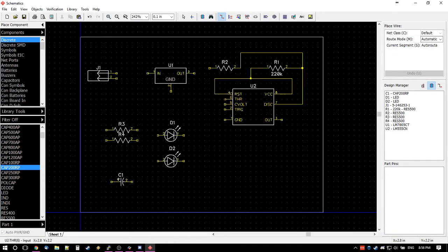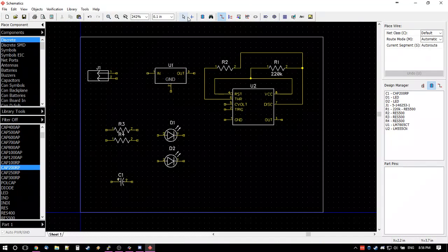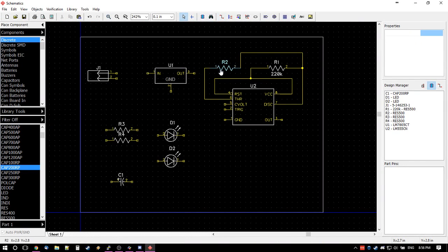So from pin 6, we're going to click like this and connect it to the other end. So that's got a value of 22K. So again, switch to default mode, click on the resistor, and then in the value box, we're going to put 22K, and then we're going to change the marking to value.